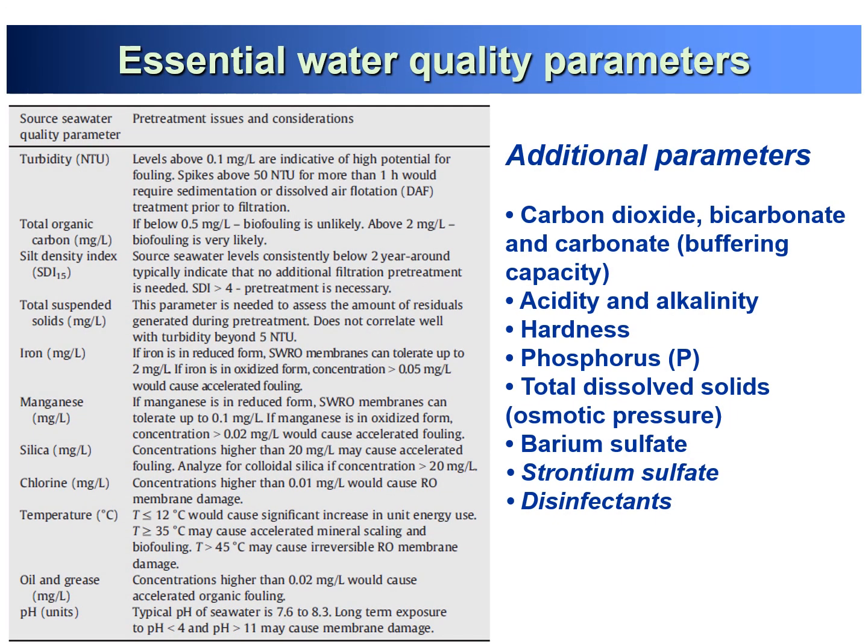And total suspended solids are needed to assess the amount of residuals generated during pretreatment, and do not correlate well with the turbidity beyond 5 NTU.